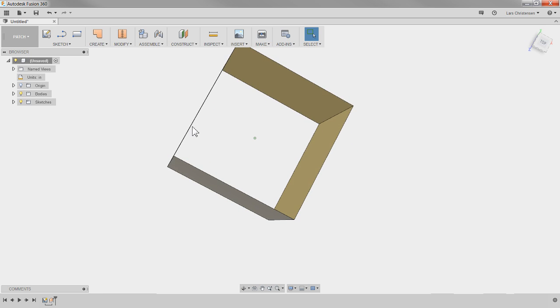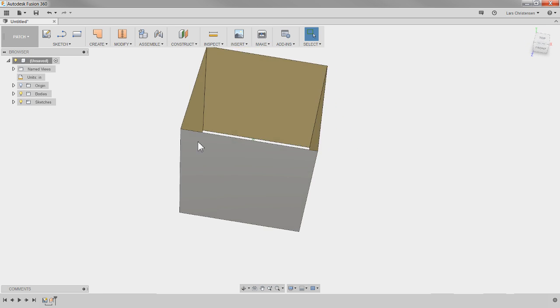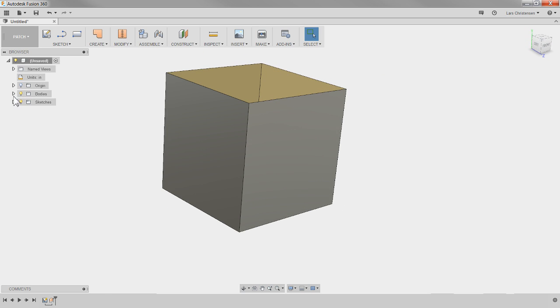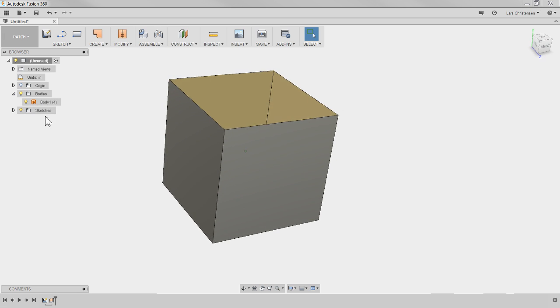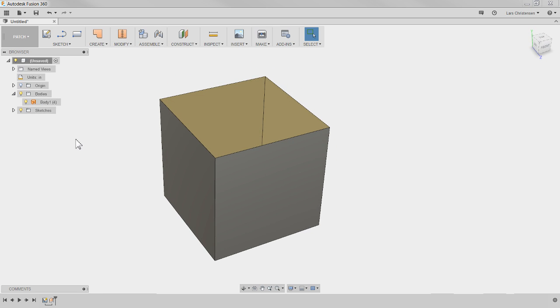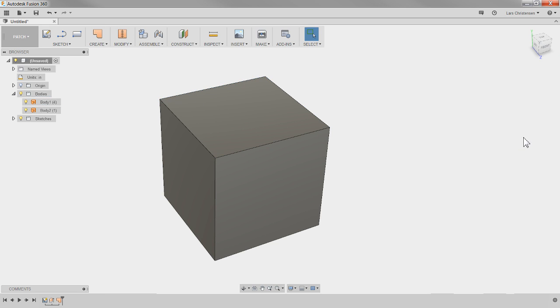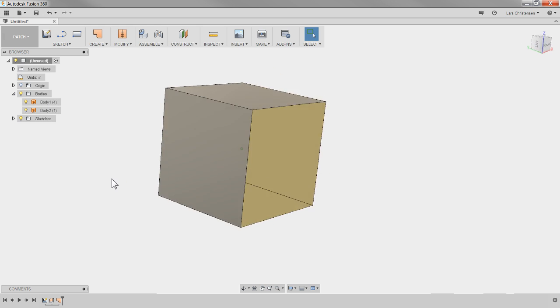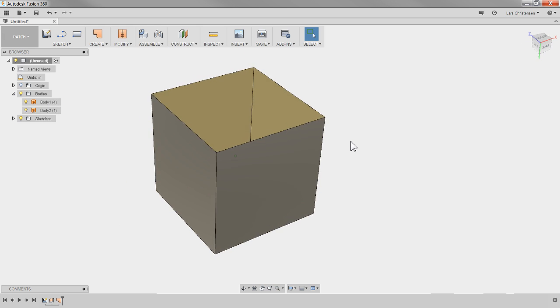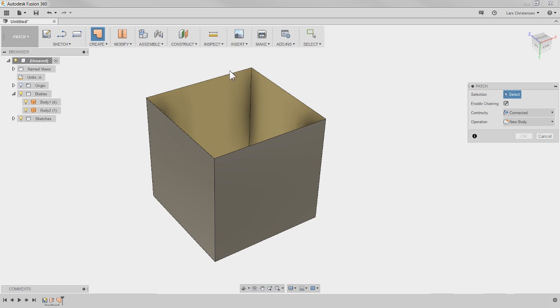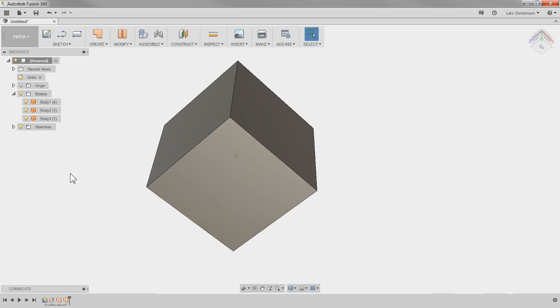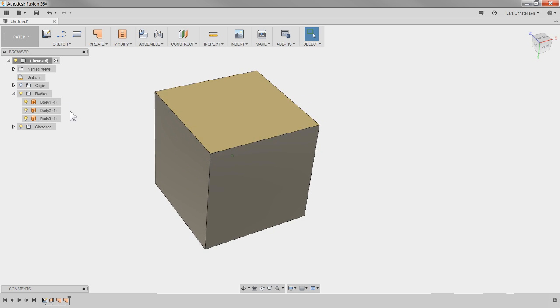You will see these walls here have no thickness to them. This is a surface wall. And if we click over in the bodies folder, you will see that we get this body of surfaces. Now, if I go in and do the patch, so I can put a lid on this, do one there, you will see now I get another surface over here. Now it's just an open box. Let me right click and repeat patch and do another one on top here. And now we've got a closed cube, but it is all just surfaces.